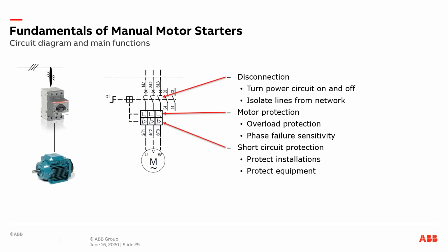So a manual motor starter is a standalone unit, and it can disconnect. It can give you motor protection, overload, and phase failure, and it can give you protection against short circuit as well. So it is a very good solution.